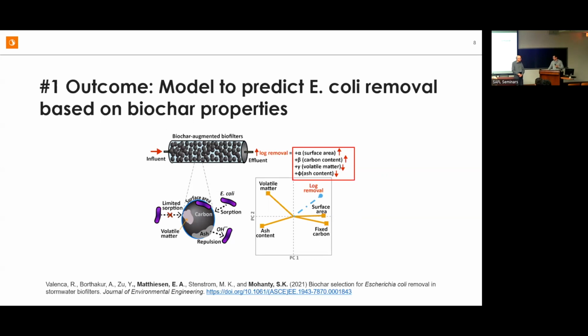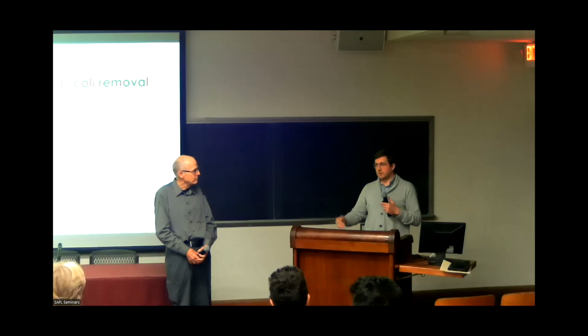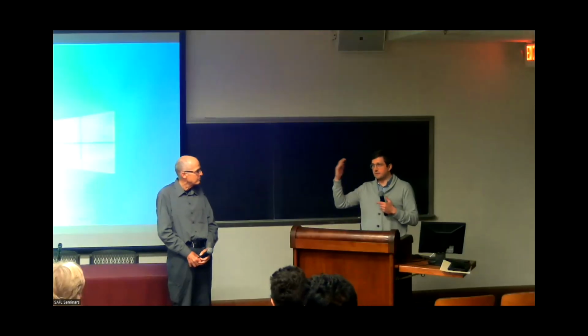No, the contact time, we realize if we have 15 to 18 inches, we have what we need. I think we design our filters long-term to pass like 2 to 3 inches per hour, especially for our pump-based filters. We make sure that our pump can operate between like 1 and 3. Some of these filters, when they first go online, could be up at 10 or 11.